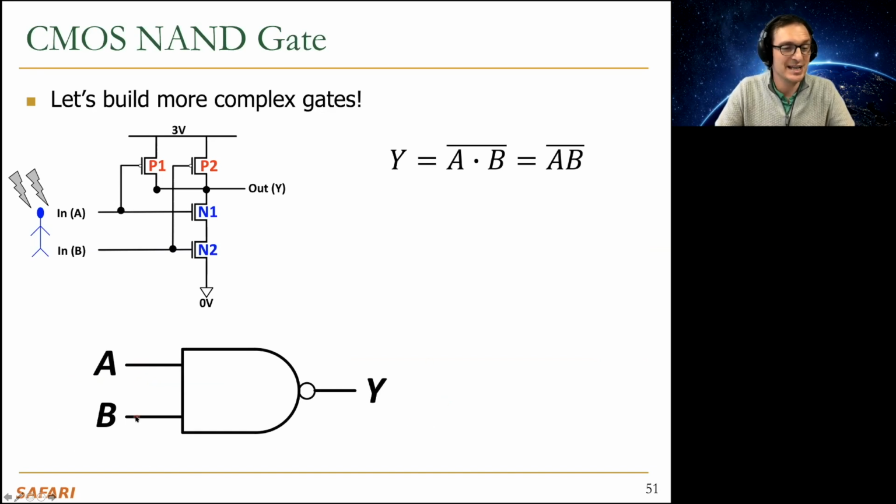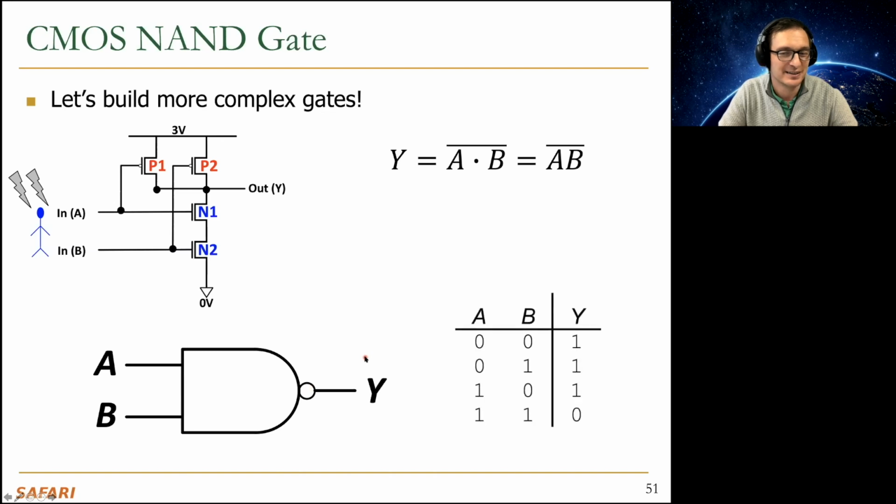Okay, and we represent this like this. So you have A, B, and we have this thing that's essentially the notation for the AND gate, and we have a bubble. Basically, this means that Y is equal to the AND of A and B complemented, or NAND of A and B. Makes sense, right? So if you wanted the AND of A and B, you basically have an inverter after this. And I'm going to show that in a little bit also, actually. Hopefully this is clear.